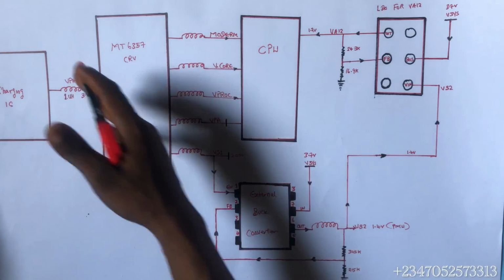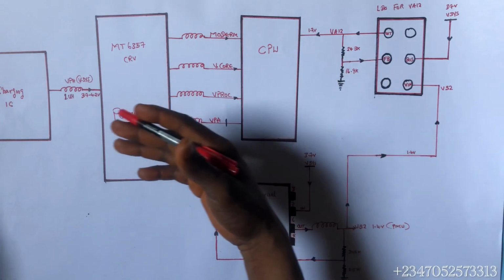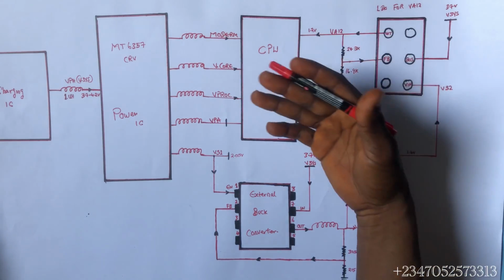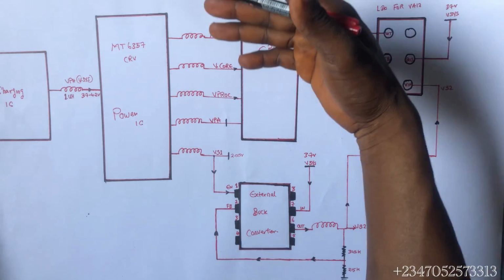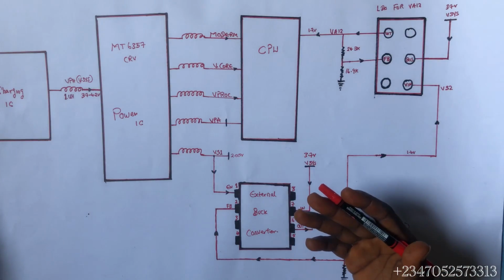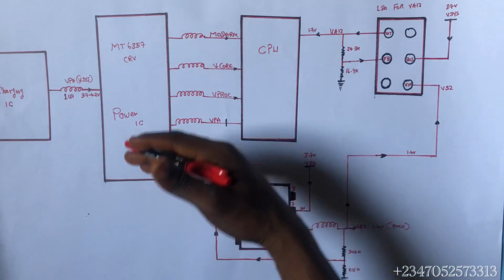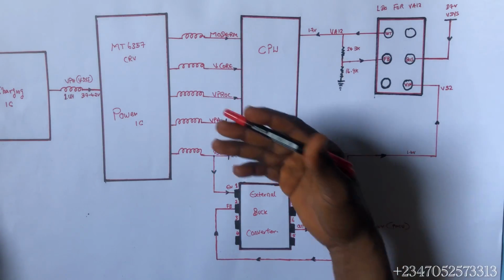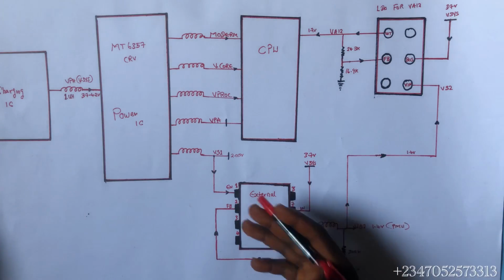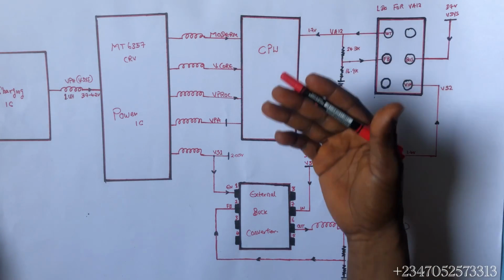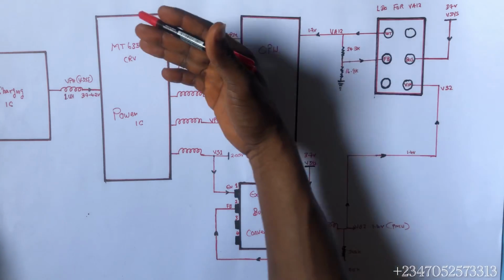Now the DC supply will give you a different reading. Let's say it will start from 0 ampere, it will increase to 30 something, 40 something, sometimes then it will drop back, or it will come back to 20, it will go back to 30 something, come back to 20. So now it means that line is faulty. So now you will not know the exact line. All you have to do is to know that maybe a line is not turning on.